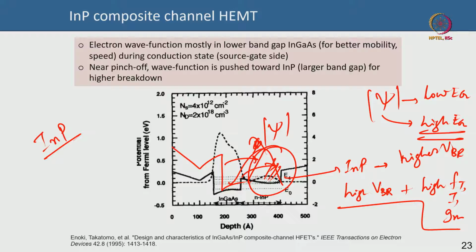So, scalability, economy of scale, cost, process maturity and so on are relatively poorer for indium phosphide than gallium arsenide. With gallium arsenide substrates you can scale it up, economy of scale is looking good, and the process maturity is really robust. So, you can have better throughput, better device output in terms of economy and cost.